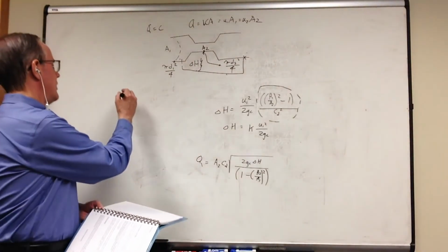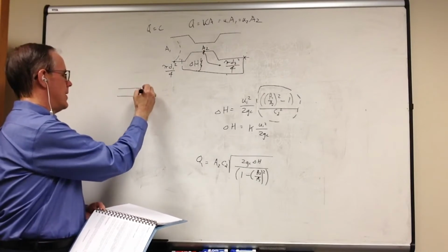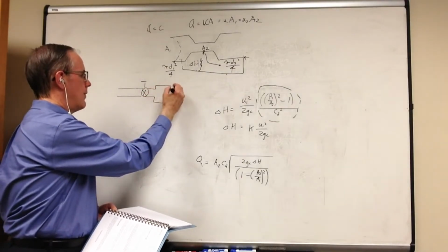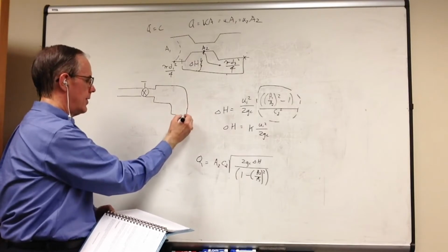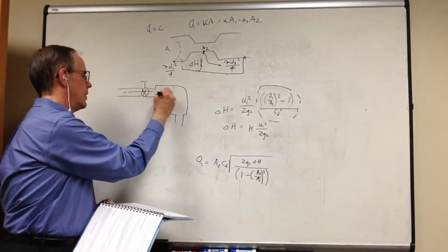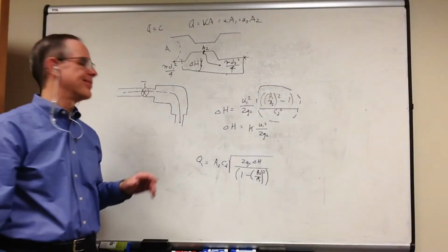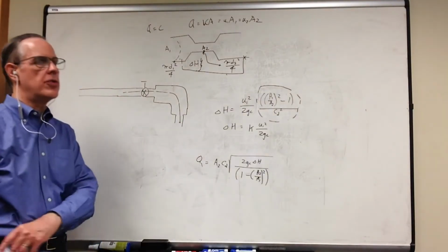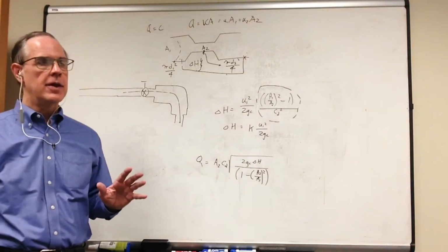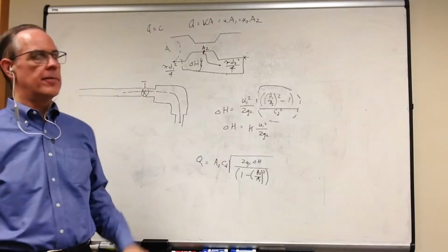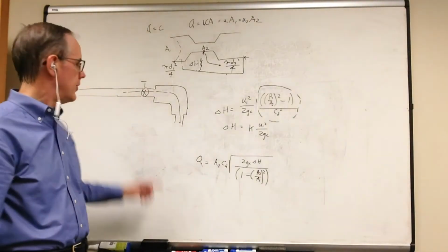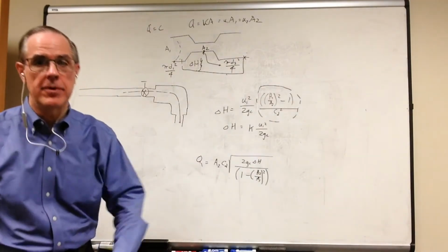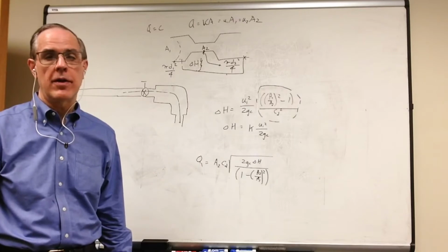If I've got a hydraulics or a fluid flow system where I've got a pipe, and then I have a valve, and then I have an increase in there, and then I've got an elbow, and then I maybe have a decrease. Maybe this thing's been kind of cobbled together and the flow goes through here. For a straight pipe, if we know the roughness of the wall or can estimate it reasonably, we can determine the losses in that pipe using the Moody charts or using equations that are based on the Moody charts. And these have been around a long time.